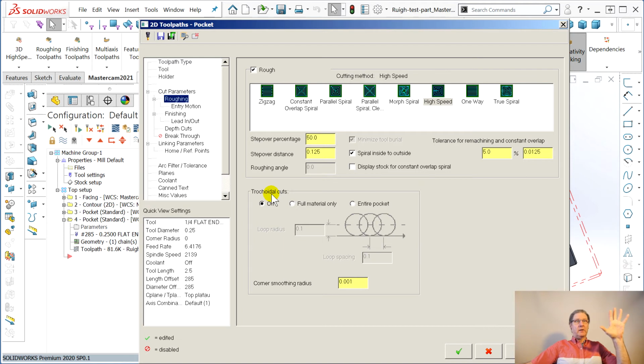Maybe that trochoidal cut is what they call this high-speed machining. You know, this thing, iMachining, is what SolidCAM does. They may have invented it. I think high-speed machining, according to my buddies, was done down in Los Angeles by the aerospace people. They figured if you get a spindle going 15,000 RPM, you can really move fast through aluminum, right? Carbide tooling. And they did that 20 years ago or whenever.